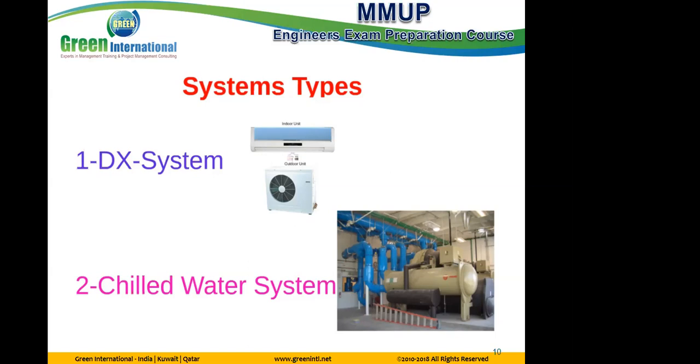You remember the simple cycle for refrigeration? Compressor, condenser, expansion valve, evaporator. Actually, the evaporator, if we study the simple split unit, is what we see in the indoor unit. So the air is in direct contact with the tubes that have the refrigerant, correct? Correct. If the air needs to be cooled by contact directly with the refrigerant, this is the DX system.